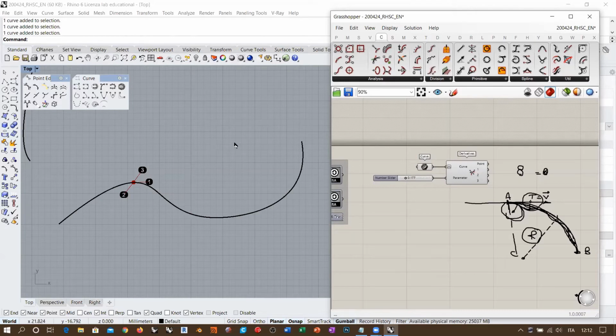But you also know that if the degree of a curve is 3, you cannot have a continuity level higher than, for example, G2, because G3 is already constant, so it's absolutely nonsensical. If you have a degree 5 curve, it is smoother, and you can also tweak the continuity of that curve to a higher level, which can be G3 and G4.